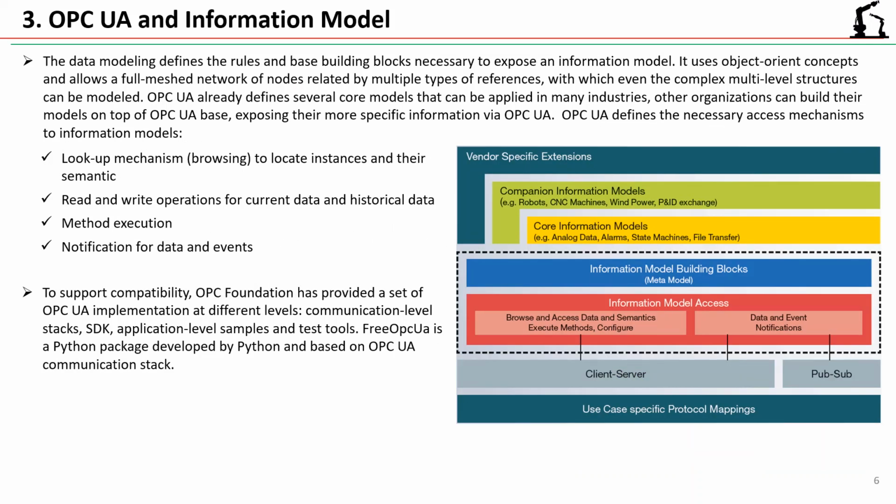The data modeling defines the rules and the basic building blocks necessary to expose an information model of a device, control system, or any other complex system. OPC UA basically borrows the object-oriented concept from computer science. It allows us to define the information model as a network of nodes with various types of references.